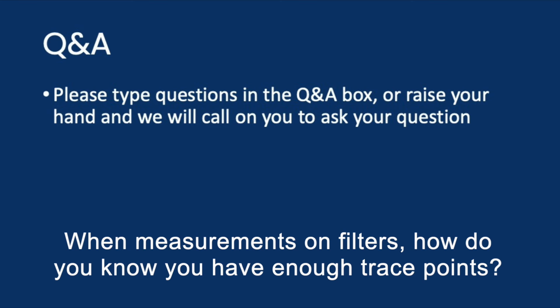And then from there, I would even just save that trace to memory. That's an easy thing to accomplish, certainly with our VNAs. And then just back down the number of points or spread out the frequency span between points, same difference, down to the point where you start losing that resolution that you need to be able to evaluate whether you can see everything you need to on that filter or not.